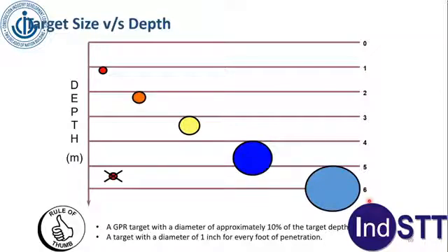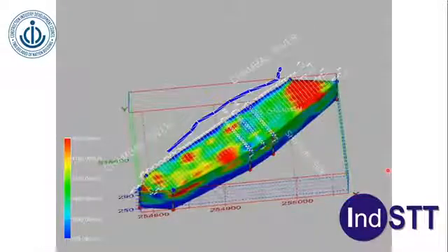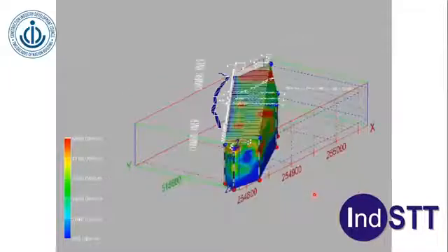It is used a lot for archaeological investigation also. It can also be used for cavity detection. So this is a cavity at 18 meters using GPR. This is 7 meters, 18 meters, 7 meters. Results of the entire geophysical investigations can be presented even like this. This is a 3-dimensional result. This was for cavity detection.